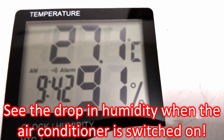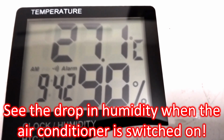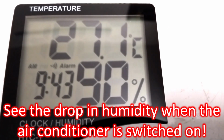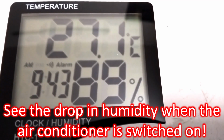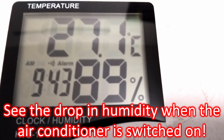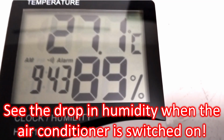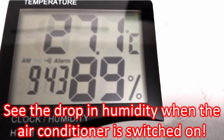A calibrated capacitive hygrometer can have an accuracy of plus or minus 2% relative humidity, between 5 and 95%. Capacitive sensors can tolerate effects of condensation and transient high temperatures, but they are subject to contamination, drift, and aging effects. Resistive hygrometers measure the change in electrical resistance of a material due to changes in humidity.